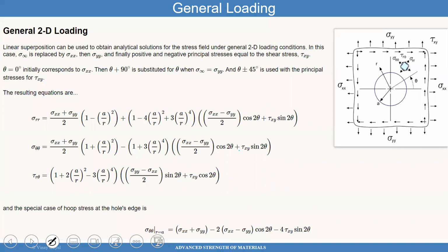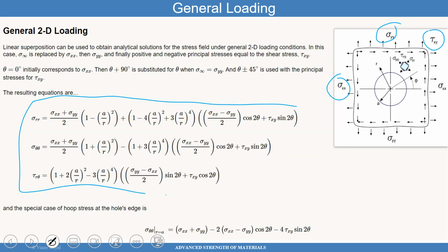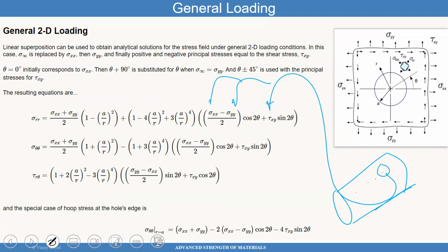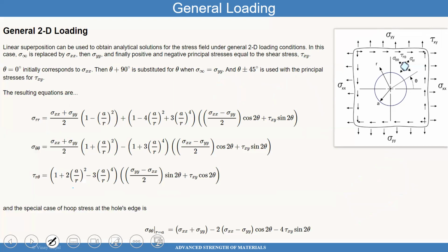In the more general case, if I have stress fields applied far field, and shear stresses applied far field, and I have this information, I can tell you what the stress state is going to be at the hole, and the equation is here at the bottom. So this is the general formula you can use for any case, which is very powerful. Say you have a fuselage you're analyzing, and I don't want to model any of the holes of the fuselage, say they're circular holes. If I know the stress states there, I'll plug them into here, here, here. I'll use the finite element code. Instead of modeling the hole, I get the far field stress, apply it to each of these formulas, and now I can calculate the effects at the hole. So rather than modeling the hole, you can take advantage of these solutions in a very simple way without having to worry about it.